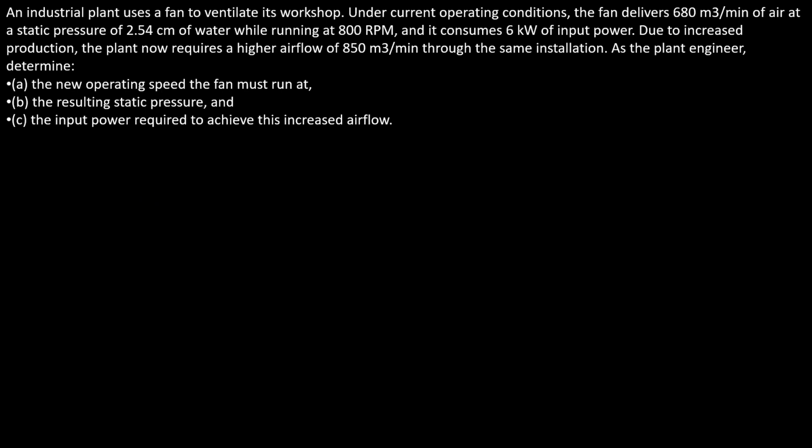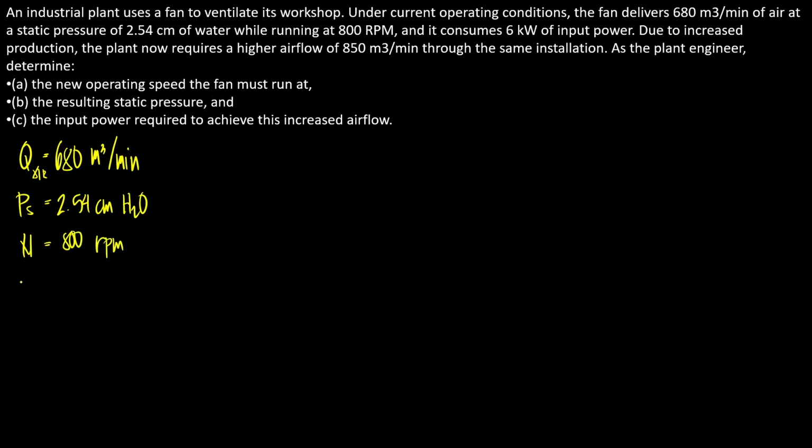Under current operating conditions, the fan delivers a Q of 680 cubic meters per minute of air, at a static pressure of 2.54 cm of H2O, while running at 800 RPM. So it consumes 6 kilowatts.